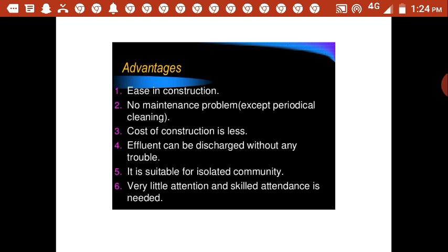Suddenly, if you dispose of waste without filling the water, the digestion process will not be proper. Once the digestion process is not proper, the treatment is highly difficult, and it will transfer the load to the other compartment.